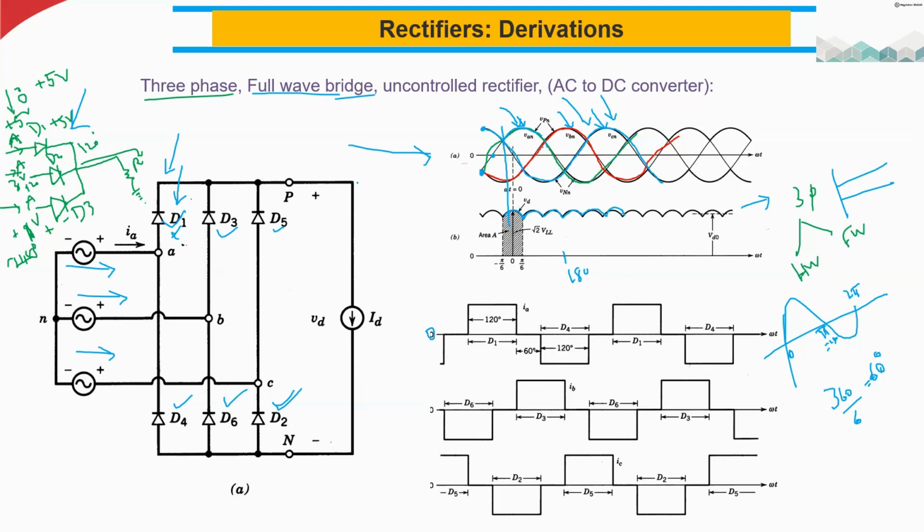The three-phase rectifier is not really important for you at bachelor level. The single phase is already good enough. That is what you are going to do in the lab. And one last thing, remember if I use these 3 diodes, then it produces 3 pulses in one cycle. If it produces 3 pulses or 6 pulses, then we can call this a 3 pulse rectifier or a 6 pulse rectifier. So it's based on the number of diodes. Each diode will create 1 pulse.